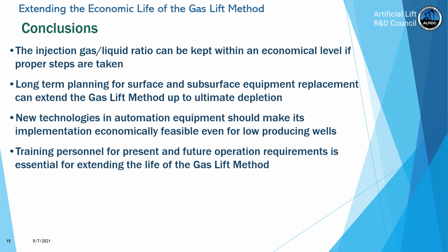Throughout this presentation, I have mentioned that we need to calculate the liquid fallback, the slug velocity, the volume of gas that we inject per cycle, the optimal cycle time, the time that the intermitter has to remain open or closed, and so on. That requires having the proper tools that you don't find in commercially available software.